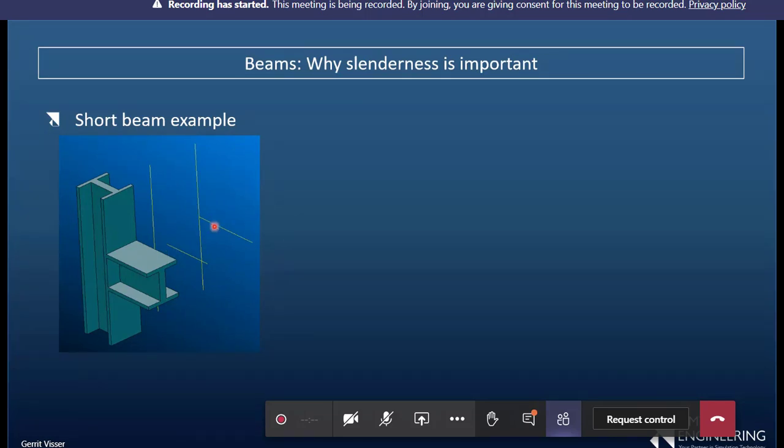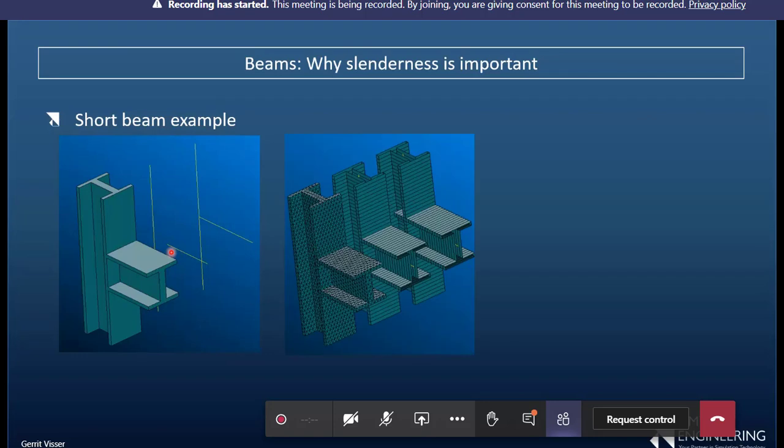So in this example, I just extended the curve all the way to the end, and then I mesh these and apply the beam properties. So this is what it would look like. I've just plotted the beams expanded. Now, notice one thing though. These little lines that you see there represent all of the beam elements. So my beam elements in the length direction are actually way smaller than I need.